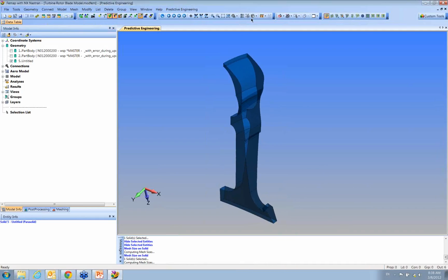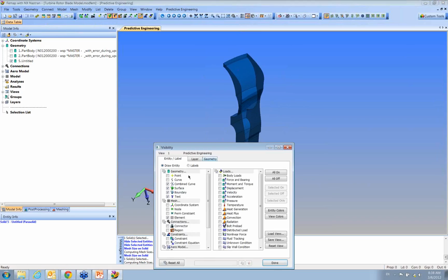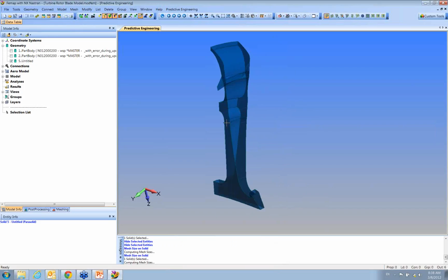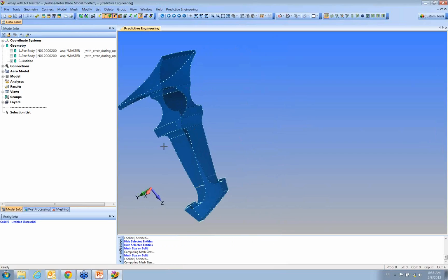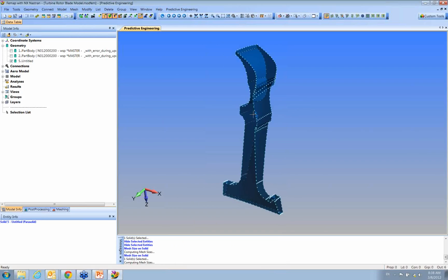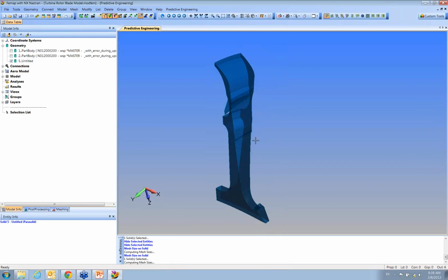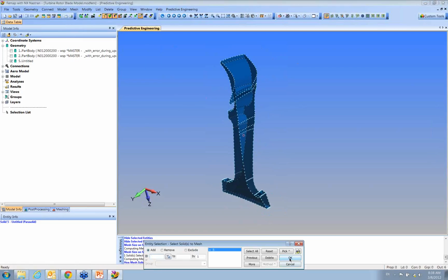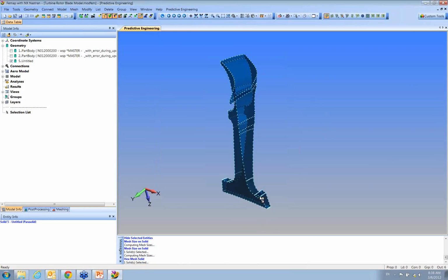And it comes up, and it shows it wants to mesh it, and you say, where are the curves? Well, it's something I blanked, like that. And it thinks it can mesh it, because it's mapped this surface onto this surface, and it's pretty confident that it can extrude a mesh through that side. And then you would go into Geometry, Hex Mesh Solid, and you pick it.